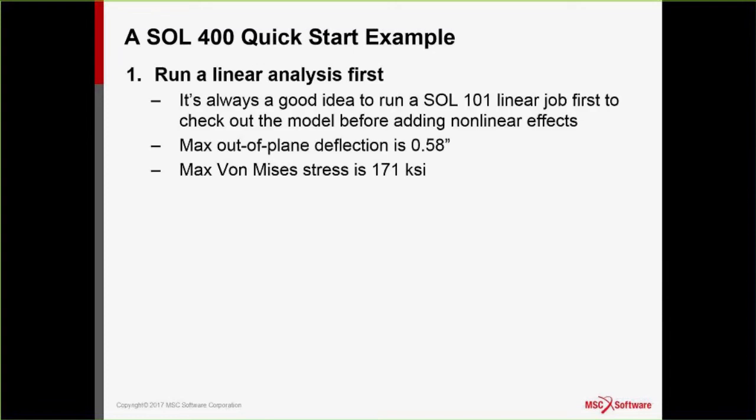Okay, first step then, it's always a good idea to run a Solution 101 linear job. Even though you're totally confident that your job is going to encounter nonlinearity, you want to resist pushing the button right away, and come back and do a Solution 101 first. It gives you a chance to check out your model, and also gives you a baseline so you can easily identify possible nonlinearities.